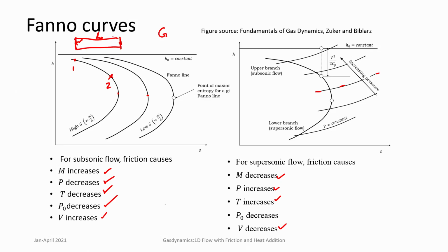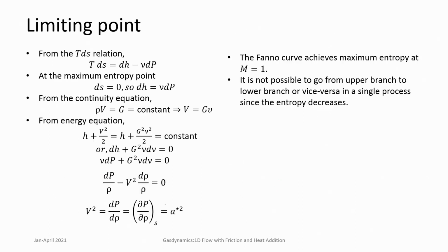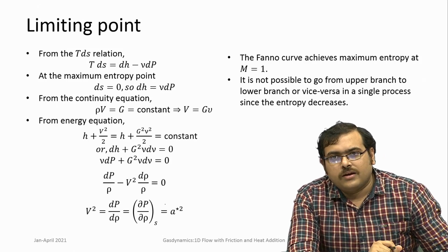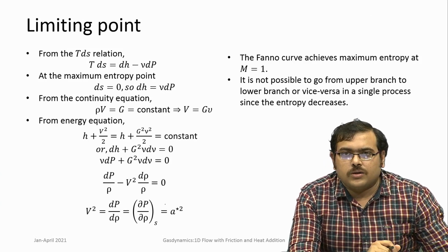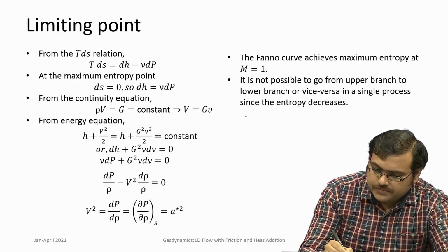Now, how we will get to these lengths, and what are the equations that will help us solve them for flow through pipes and so on, we will soon come to it. Here we are discussing thermodynamic aspects of Fanno flows, and just by means of a thermodynamic curve, an HS or TS diagram, we can know all that is to know about this particular flow. Okay. Now, we have to look at that particular point.